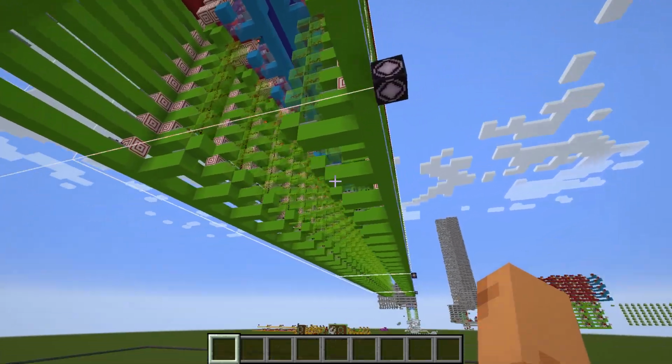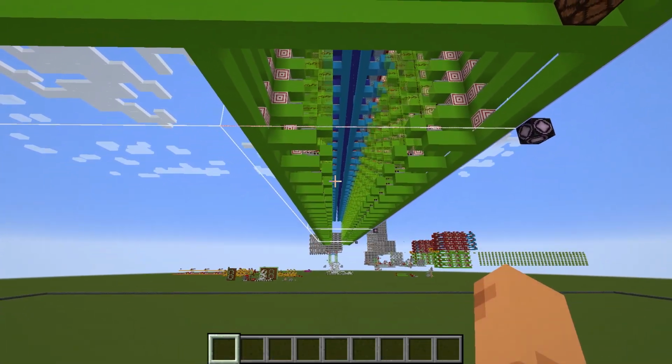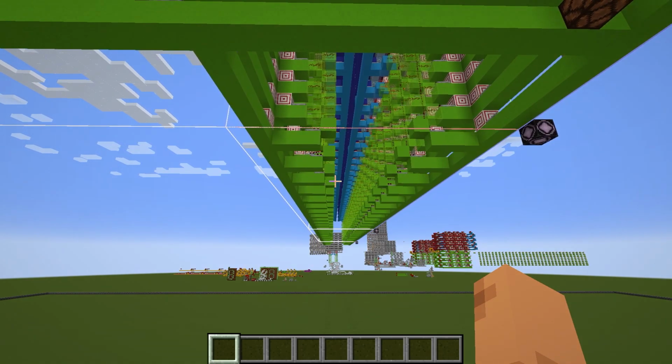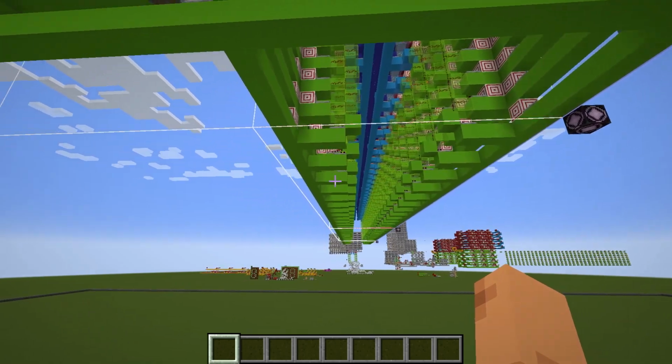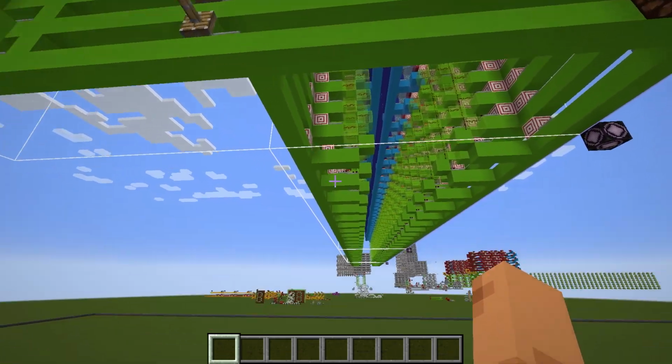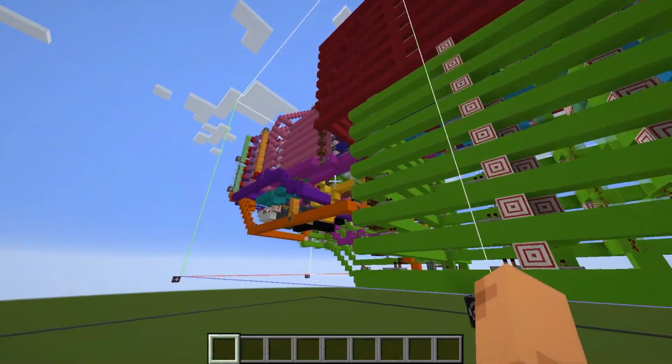And that's somewhat arbitrary, but oftentimes architectures will decide an alignment for instruction memory, which is what this is basically doing. And so all of our instructions are aligned on a 2-byte boundary, such that the even bytes are always the opcode and the odd bytes are the data part.